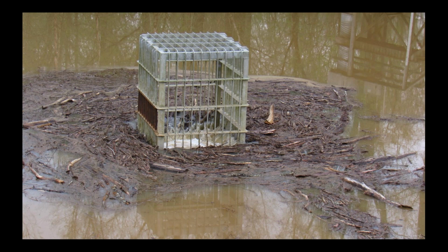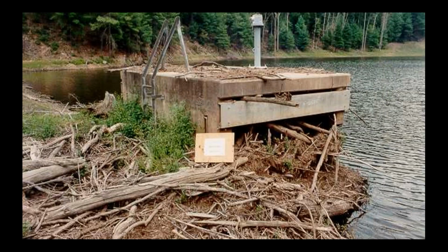Now, there still is the backup, which is the auxiliary spillway, but both spillways are supposed to be doing their original function. Now, here we have a larger riser structure with the trash rack. Now, the trash rack's doing its job. It's preventing the debris from accumulating. But obviously, if we were inspecting this dam, this would be a maintenance issue. We want to make sure that the principal spillway continues to function, so that we do have the flood control storage in place, and the project can do its job. So this would be a deficiency.